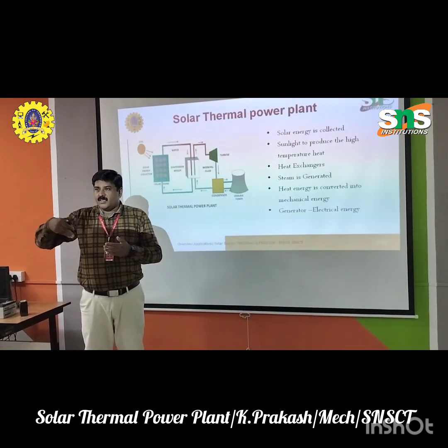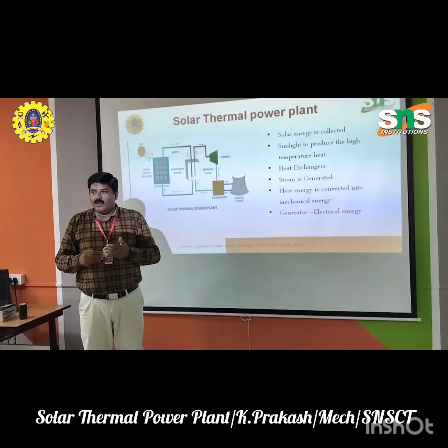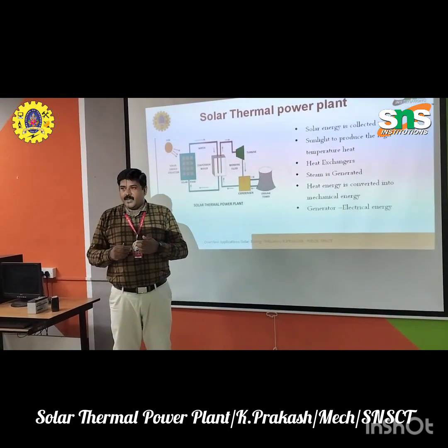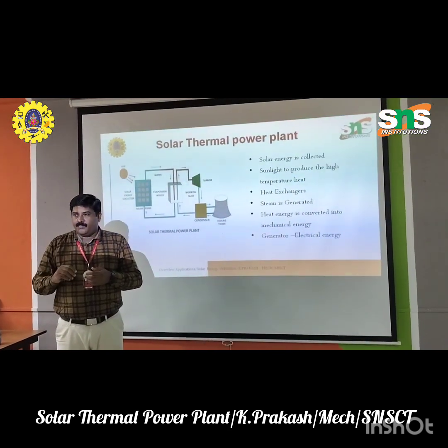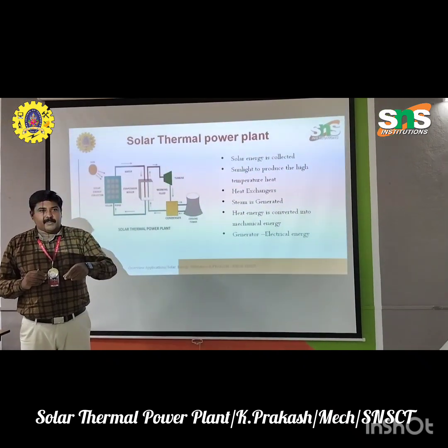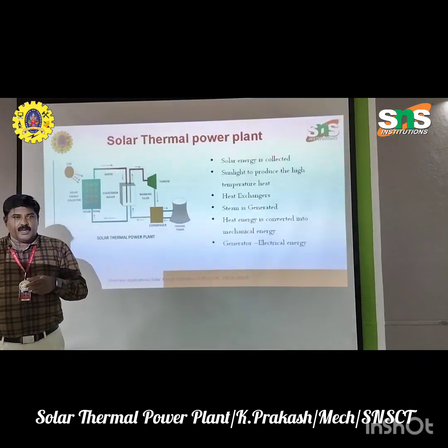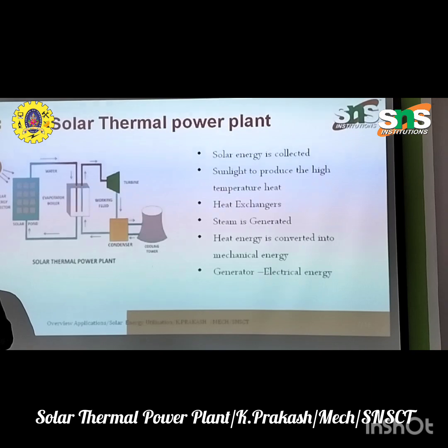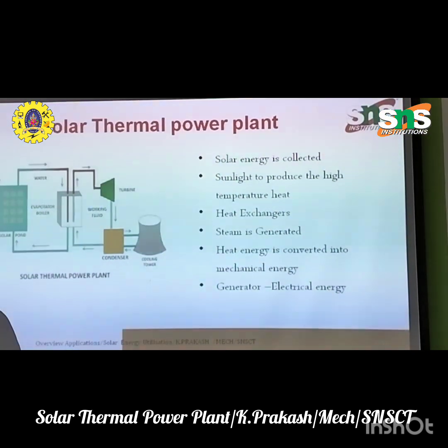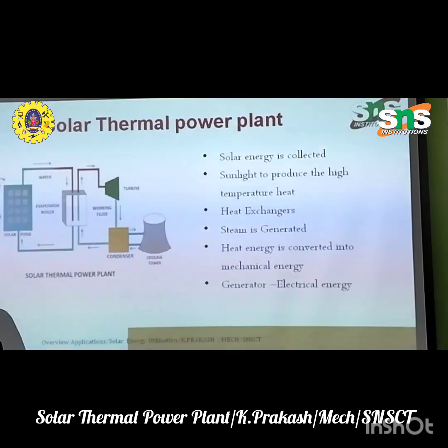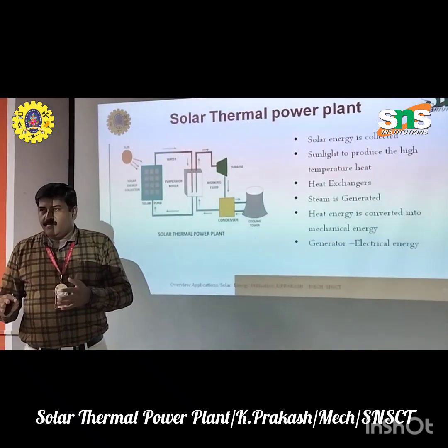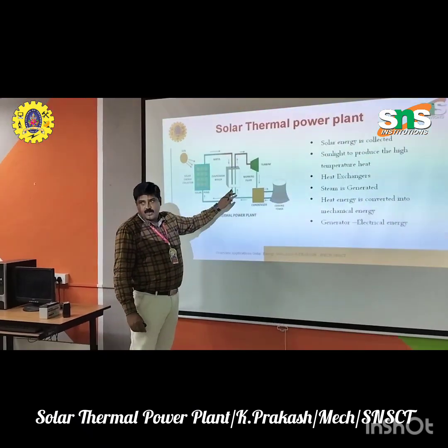The air in contact with the pipes of the radiator takes away the heat. When the hot fluid comes, heat is taken away by the air from the radiator, and then the cold fluid again goes to the engine and absorbs the heat. Thus the heat is liberated. The same working principle is used here.